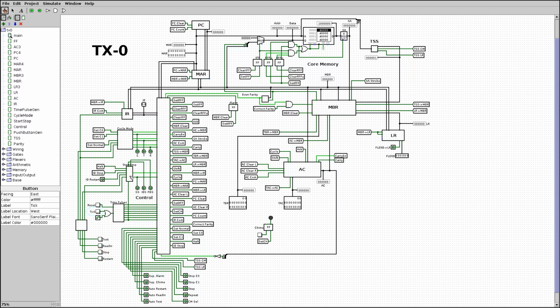Next we have the start-stop logic, which decides whether the machine is to halt or set running. And as we have seen, the start-stop flip-flop SS indicates that state, the standby versus run state. But we only want to change this SS flip-flop at the end of a complete cycle, so at TP8.